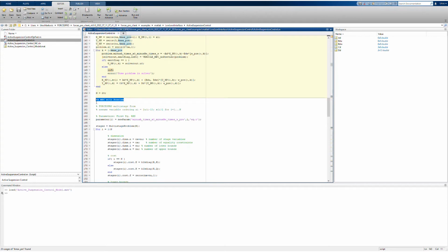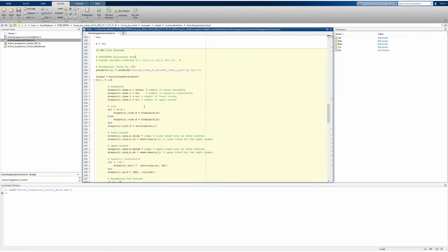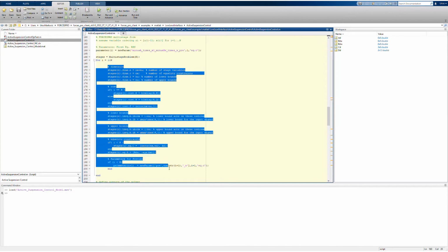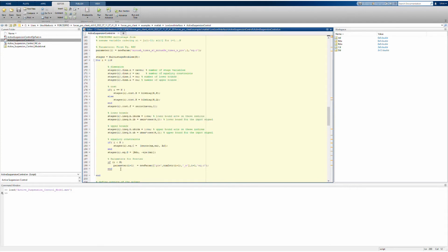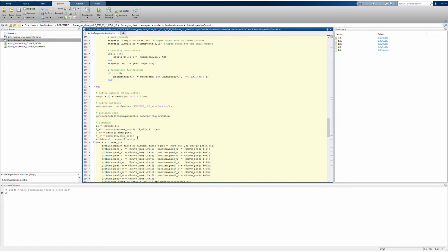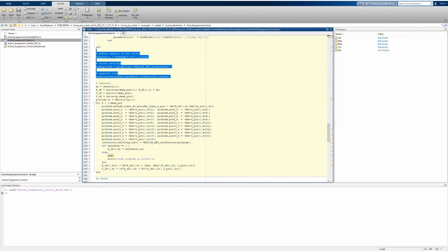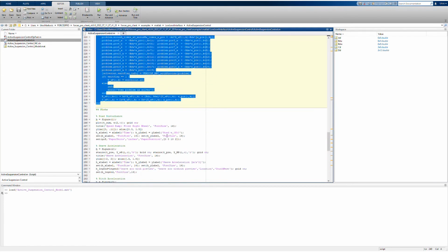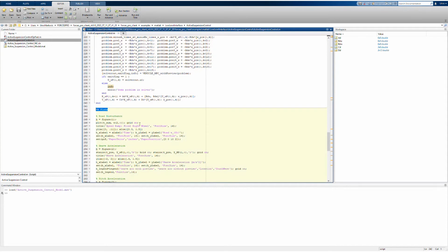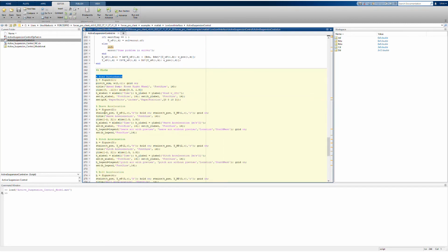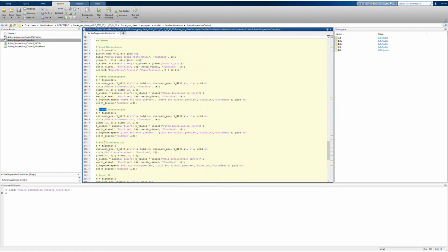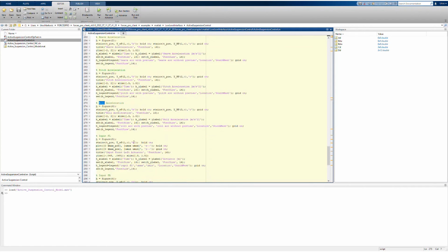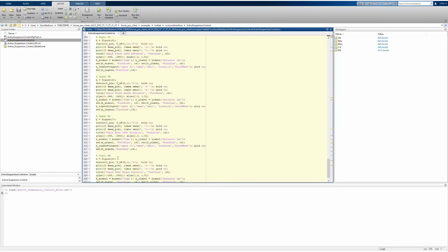As the next step, we develop the MPC with preview. It's done in an almost identical fashion, with the only addition being the parameters for preview. We then follow the steps from the previous video in order to simulate the model. Finally, the remainder of the script are the plotting functions for representing results. In particular, we graphically represent the road disturbance, heave, pitch, and roll acceleration, as well as the control inputs for all 4 wheels.